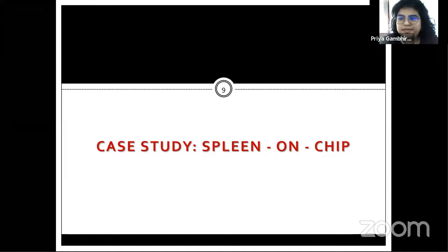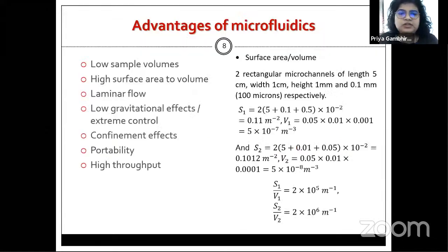I should have mentioned it before. So we have lots of pumps. Just like you need a pump to push blood within your blood vessels, you need a pump to push any kind of fluid. Nowadays we have lots of pumps available. The most common are called syringe pumps. They are a setup where you can put a syringe full of fluid, attach it on the pump, and then it slowly pushes the plunger at a given flow rate. You can actually go down to flow rates of microliters per hour. And then the other end of the syringe, using tubing, you connect to the microfluidic device.